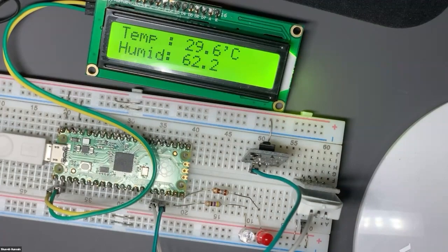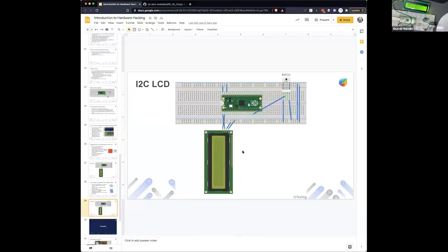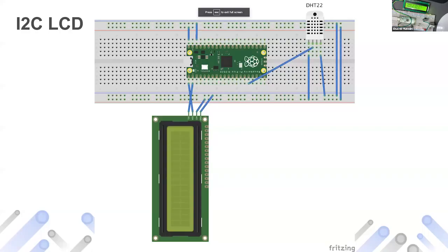Yeah. So anyway, let me start sharing my screen. We are done. So we looked at like 10 different examples. Awesome, folks. So this is the DHT22 wiring diagram. It's very simple. You have positive and negative going to the DHT22, a single data wire connected to GPIO 13, and that's it. That's the wiring. You don't need anything else.